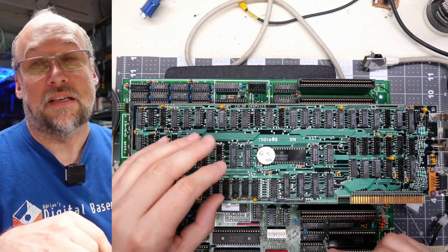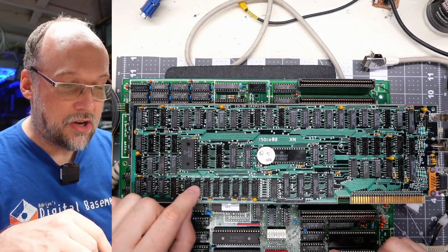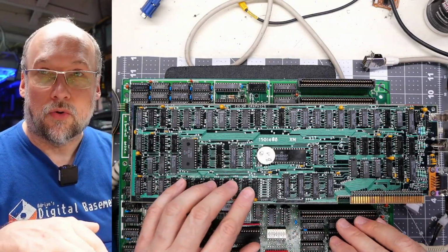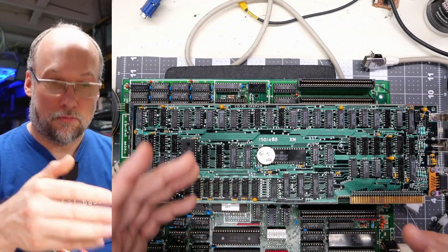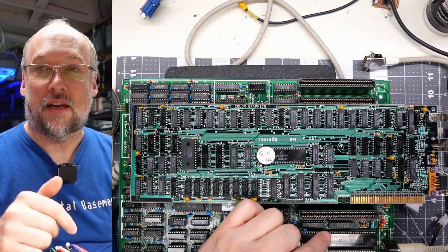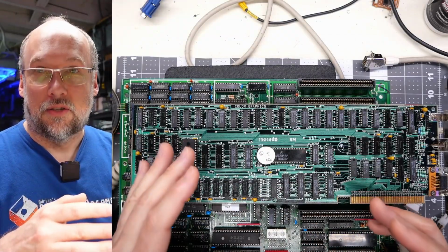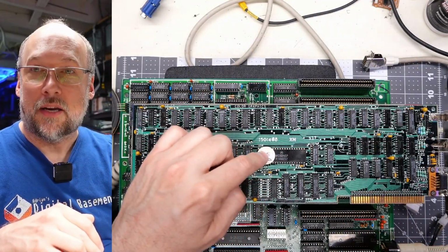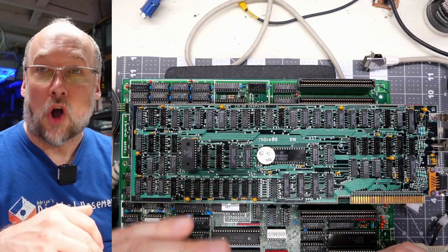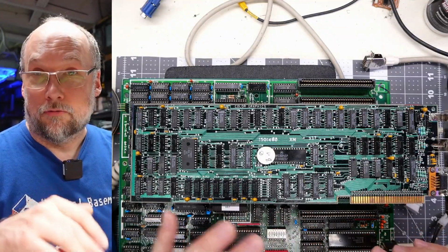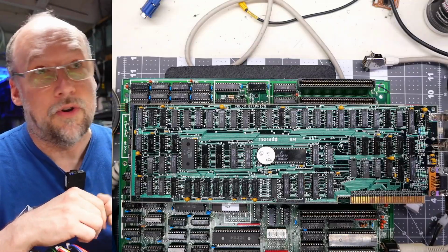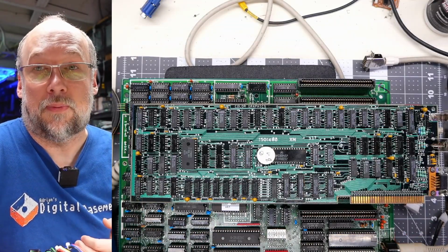Now the problem happens in 80 columns mode. I guess there's just not enough bandwidth with the chips on this thing. So when the CPU goes to read or write from the video memory, which is mapped directly into the address space of the 8088, that access to the RAM causes interference while the CRTC, this chip right here, is refreshing the screen. So as it's drawing the text screen, any reading or writing to the memory is going to cause snow. And that's the CGA snow you probably heard a lot about if you've ever used PCs.